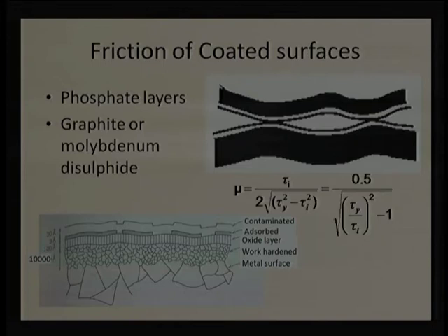If you are using Teflon, naturally Teflon in powder form will come out, and it will be worn out from the coating surface. Similarly, if you are using molybdenum disulfide and there is a rubbing condition, molybdenum disulfide will be slowly removed from the surface. The same thing happens with the graphite surface also. So in gears particularly, we cannot avoid the wear.